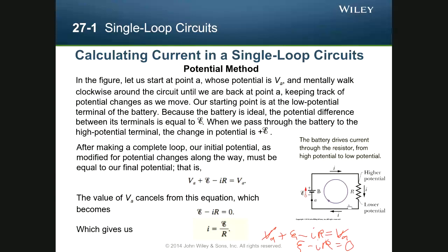And say you went around the opposite way. You went around the circuit this way. If I'm going opposite the way of the current I assumed, then this term will actually be positive, right? But in that world, this term is positive because we're going from lower to higher potential. And then from here, we'd be going from higher potential to lower potential. So the signs would flip, and you'd essentially get the same thing. You're going to want to be careful with this.